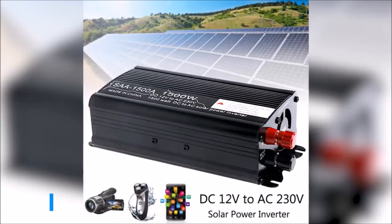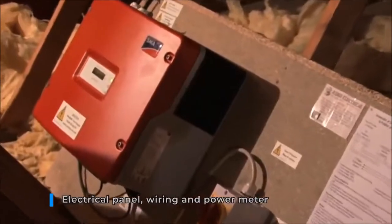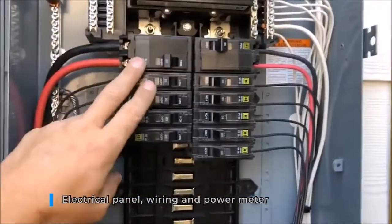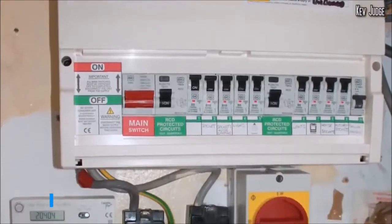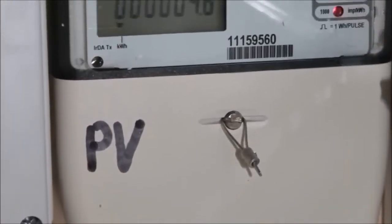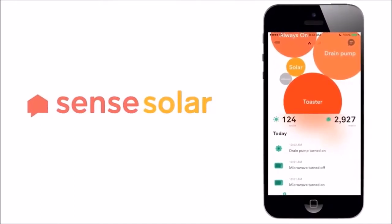In order for the AC electrical current to be distributed to the grid or to the house, an electrical panel with the necessary switches, circuit breakers, and wiring must be installed, while a power meter is used to measure the electricity produced from the installed photovoltaic system. Many modern systems have handy apps for your phone so you can see exactly how much energy you are producing. It is quite satisfying. This leads us to net metering.